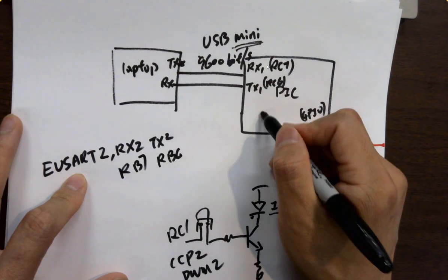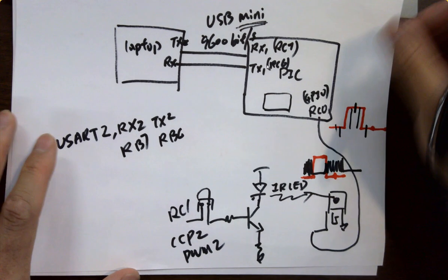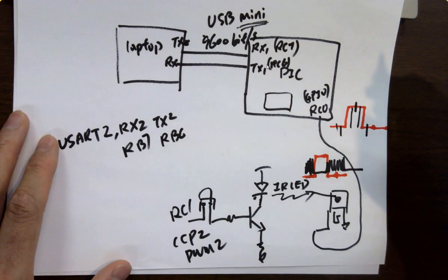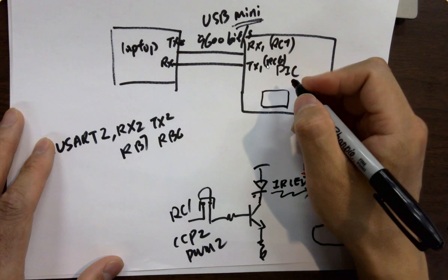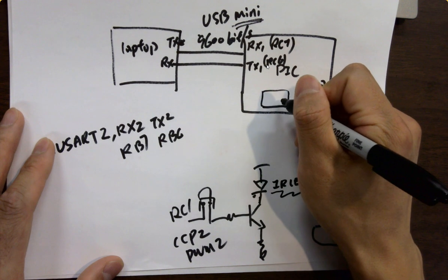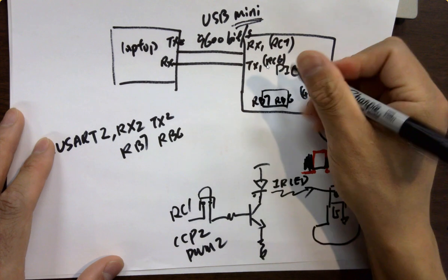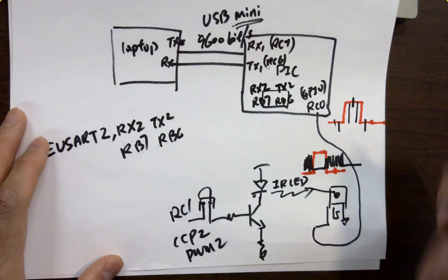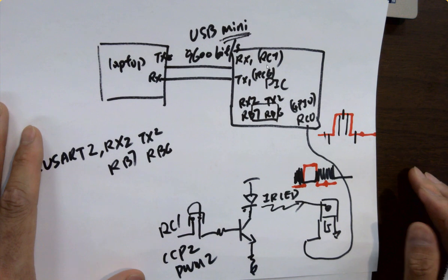So you have a UART module. If you have programmed any Verilog, you know that it's digital circuits. The UART module is digital circuits, with all the buffers and everything. That's a module, a block taking a certain area. You have RB6, RB7, which serve as TX2 and RX2. Okay, so which one do you want to use here, and for which purpose?